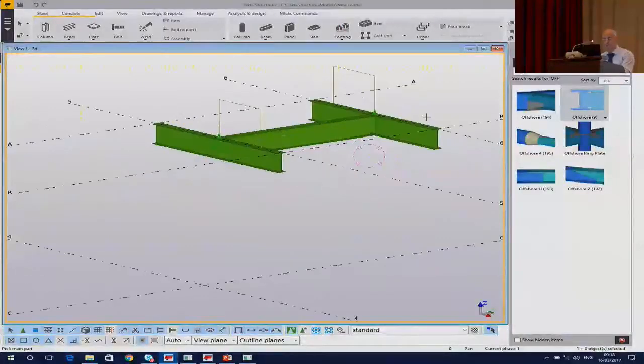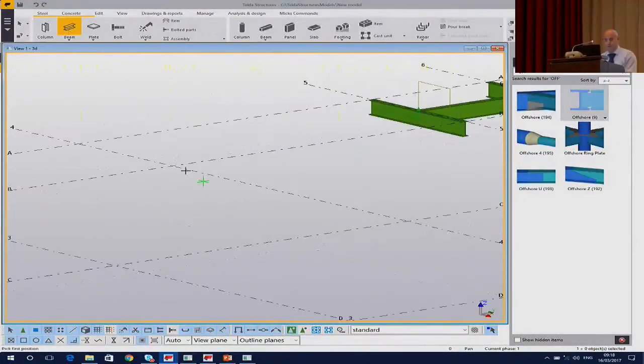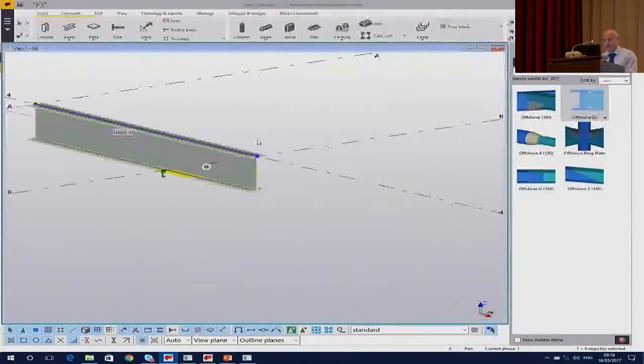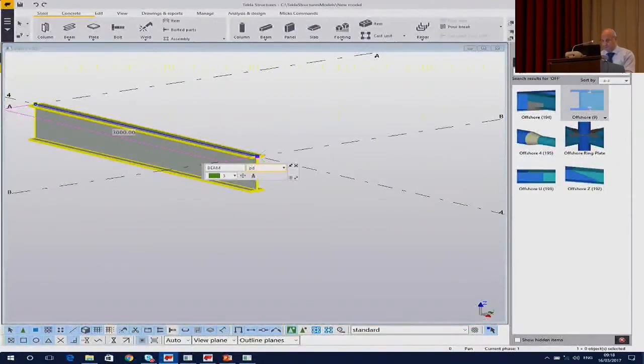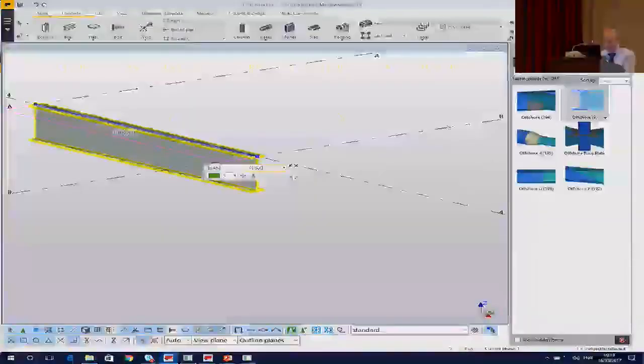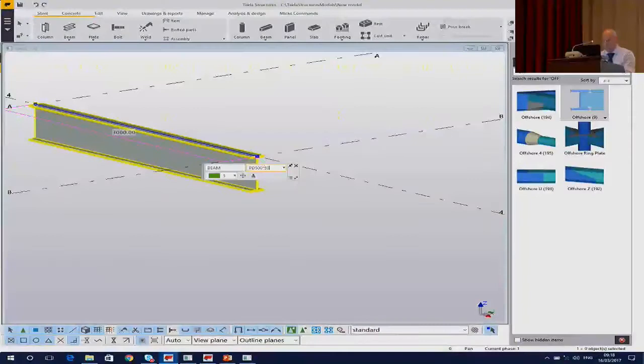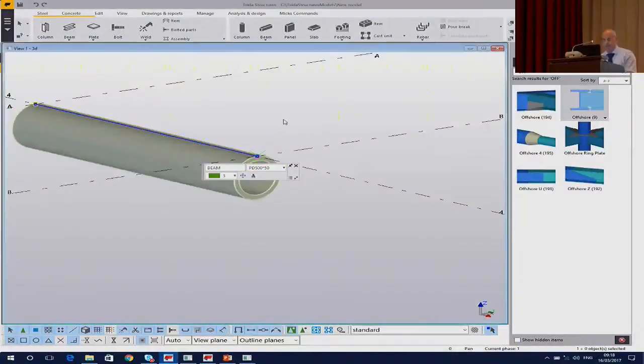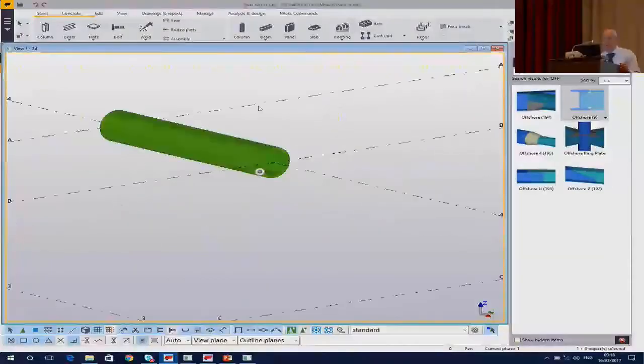That's the same for, let's say, tubular sections. So let's just click on here first of all, put a beam in there. What I'm going to do is I'll click on this, and I'll change this into a pipe diameter, let's say 500, let's put caps on there actually, 500 by 50 millimeters thick. So now it's a pipe. You can change these profiles into anything you want. Let's put that about the center, so now I've got a pipe there.